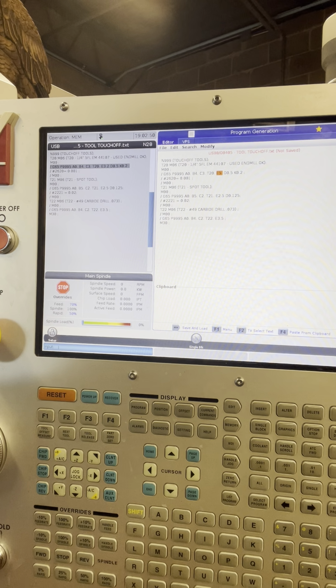So the good thing with drills, anytime you're doing the C2, which is basically the drill touch off, it's just coming down and touching. I don't know how yours does it, but mine stops a half inch before and then spins backwards to touch. Yeah. So on the drills, the estimated length means absolutely nothing.